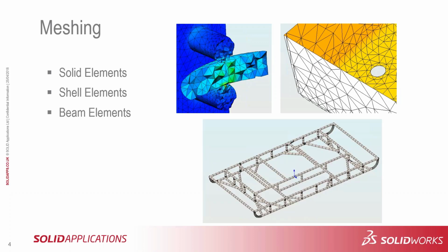And then beam elements does a similar thing for beams. So basically it treats beams as stick figures, and it breaks the stick figures up into lengths. It knows about the cross-sectional profile. Is it an I-beam? Is it an L angle? Is it a piece of square tube? And it knows the properties like the modulus of elasticity of the material and the moments of inertia. So basically it again is a calculation engine that works with the beams, and the beams of course are all tied to each other with joints. And that's handled inside the program.